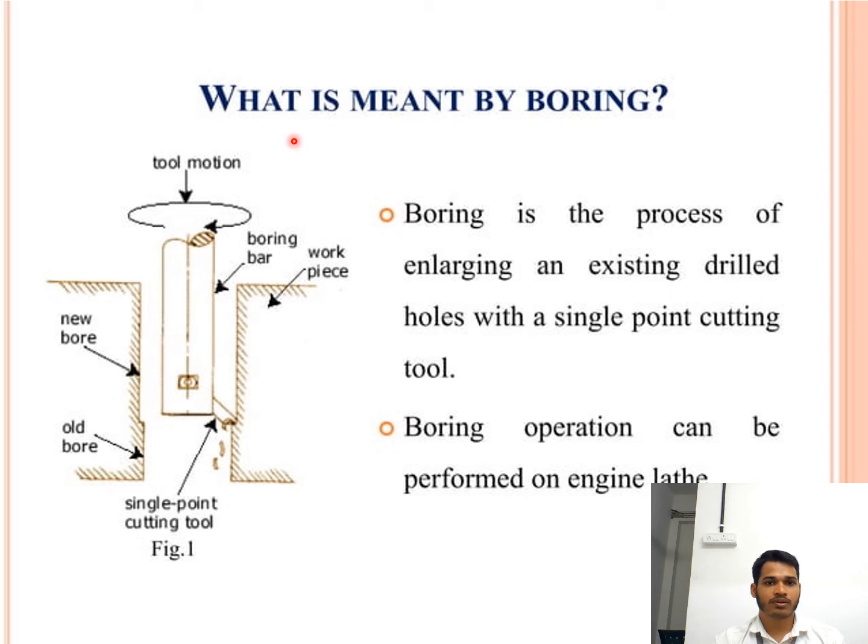Next, we will discuss boring. What is meant by boring? Boring is the process of enlarging an existing drilled hole with a single point cutting tool. So when we require a larger diameter hole, we use the boring process. The hole is first made by a drilling tool, and after that, a boring tool is used to enlarge the hole. Boring operation can be performed on an engine lathe.